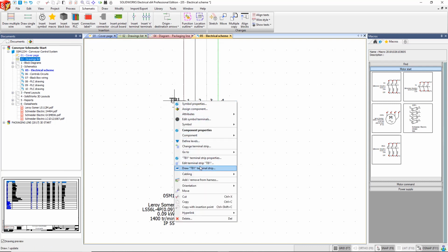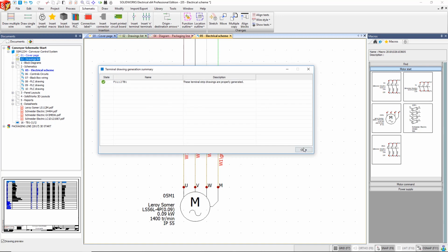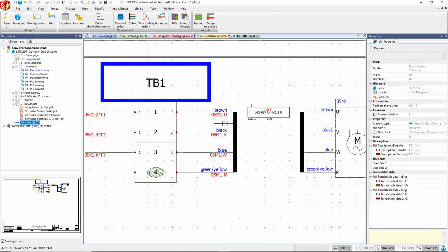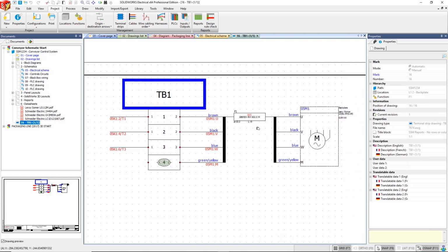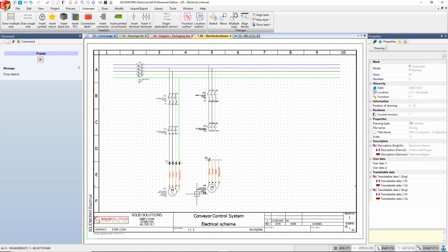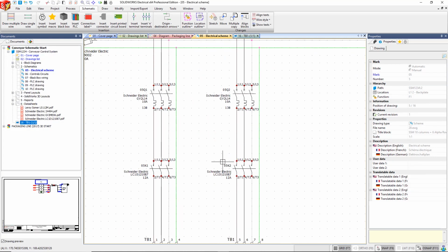I can even publish a drawing sheet which shows me all the connections in a graphical format. This is great for wiremen to follow and gives them all the information they need to be able to wire up this on a physical prototype. Again, in the software, it's really quick and easy to reuse parts of a circuit. I can simply box select items, copy them, and paste them. And this gives me brand new components.